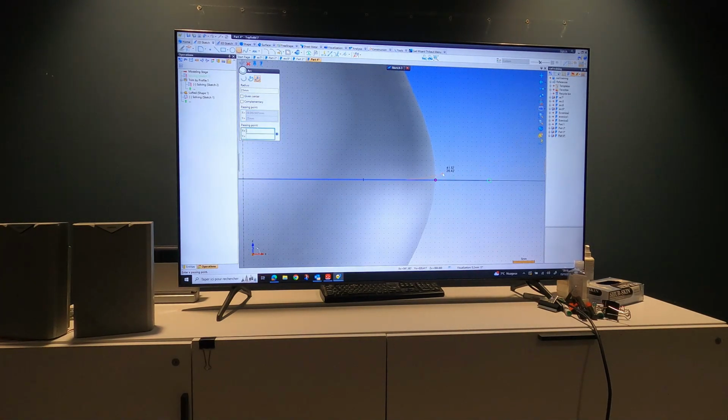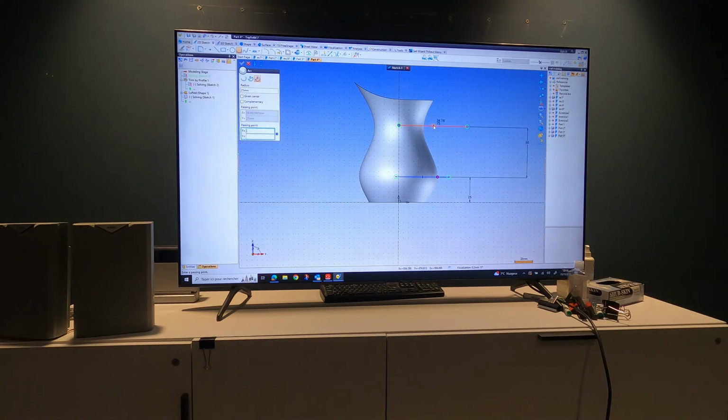Okay, and then the second point is up here somewhere, and then pull your picture down. Maybe it's because in that sheet it has a fixed radius. So if you go back to your radius tool again, on the left-hand side I think it says free, so click that. Okay, so you had a fixed radius, so as soon as you put 2 points, it said, well, this is a radius, but we don't know what the radius is.